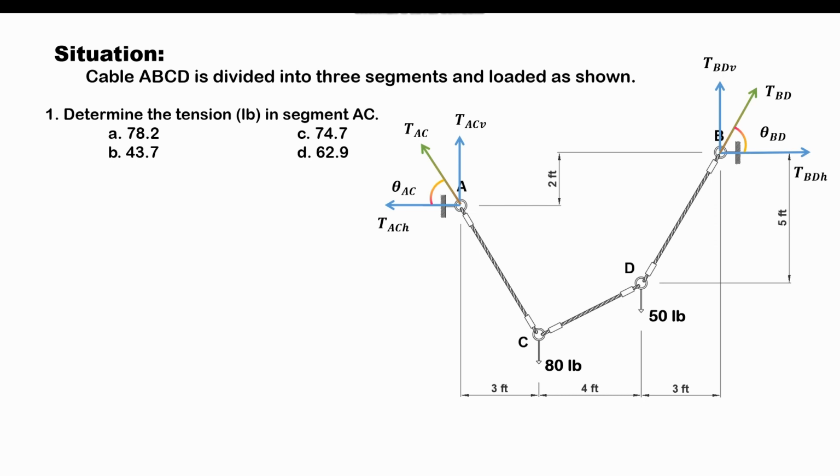Where do those equations come from? Basically, those equations will come from the equations of equilibrium. If we pick the right equation, some of the unknowns will be eliminated. And basically, what we can use among the equations of equilibrium would be the summation of moment. Why? Because if we take a moment about a point where some of the unknowns that we are not after can be eliminated, only the unknowns that we are after will have a moment.